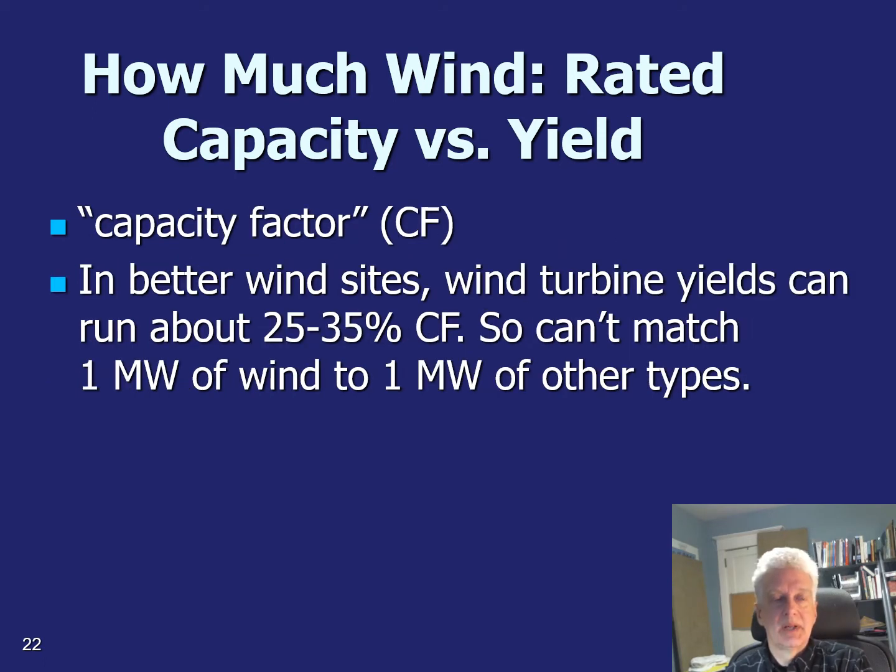So when you're planning the capacity of an entire regional power grid, you can take the capacity factor that a wind turbine is expected to work at and use that to say how much total power the system will have available on average over time. You can't take a 1 megawatt wind turbine and claim that it's contributing 1 megawatt of capacity to the system, because it will only operate at its rated nameplate capacity some part of the time, a few days a week kind of thing.